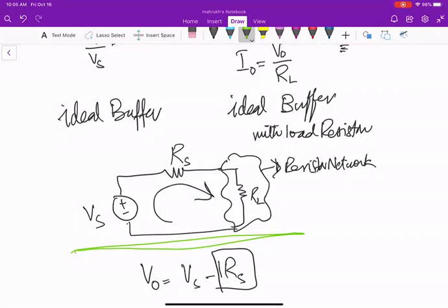Once you are doing experiments, you will learn why op amps are important, because I know it's hard to process how input current can be zero, and if input current is zero, what's the purpose of getting it at an output, right? But the idea is to remove the dependency of the output load voltage on the input or the source voltage.